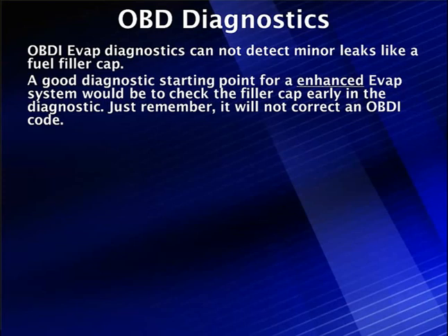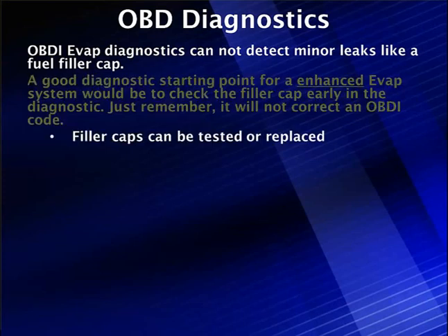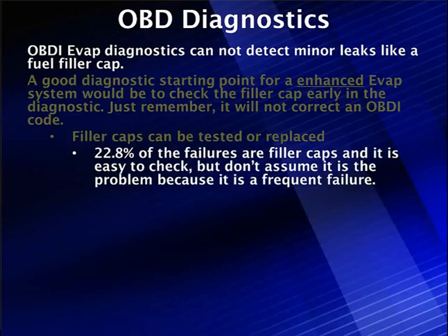It's never, 100% of the time, going to be fixed by a gas cap. They can be either tested with a tester or replaced. But if you replace it, how are you going to verify that the replacement did something? Like we said, 23% of the failures are filler caps. It's easy to check, and we can replace it.